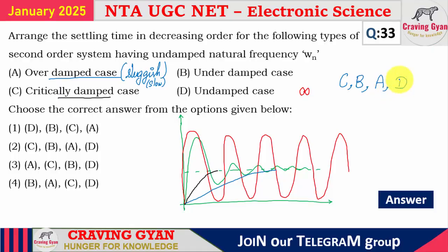So in UGC NET, the key answer they have given is CBAD. Unfortunately, this is not correct. Why? Settling time we have to arrange in decreasing order. Nothing but which one is more? Settling time is more in the case of which one? Undamped case. So it should have been something like DABC. But they are arranging from lowest to highest. So this should be in increasing order. Question mistake is there and options also mismatch is there. Okay.